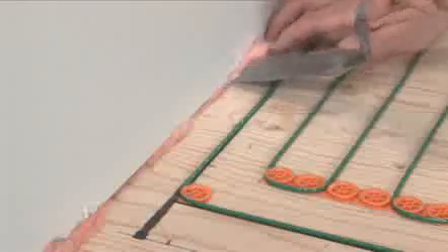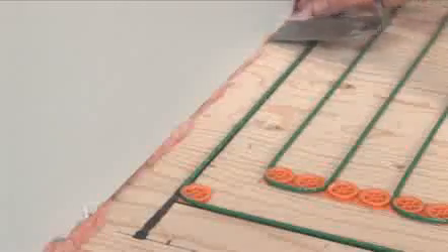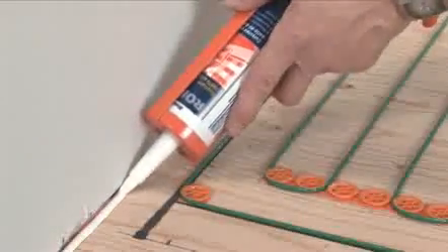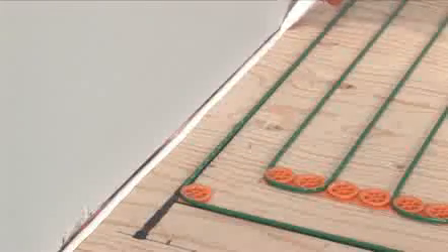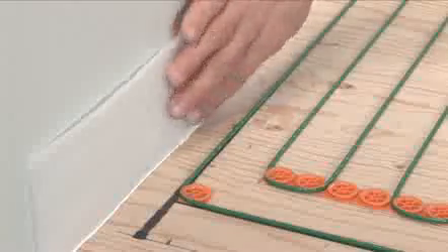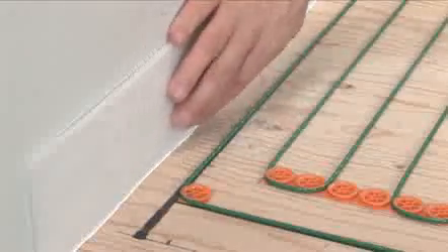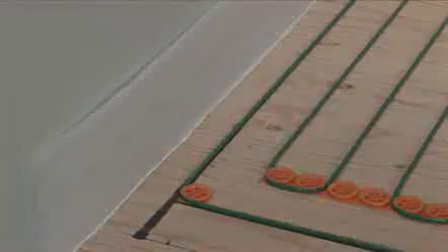Let's conclude with polymer-based self-leveling underlayment that works with all types of floor coverings. Prepare your floor before pouring the base layer. Fill all holes with fiberglass. Run a bead of silicone between the walls and the floor. Glue a foam sheet along the base of the wall. Apply a primer coat on the entire floor surface and let it dry as per manufacturer's directions.